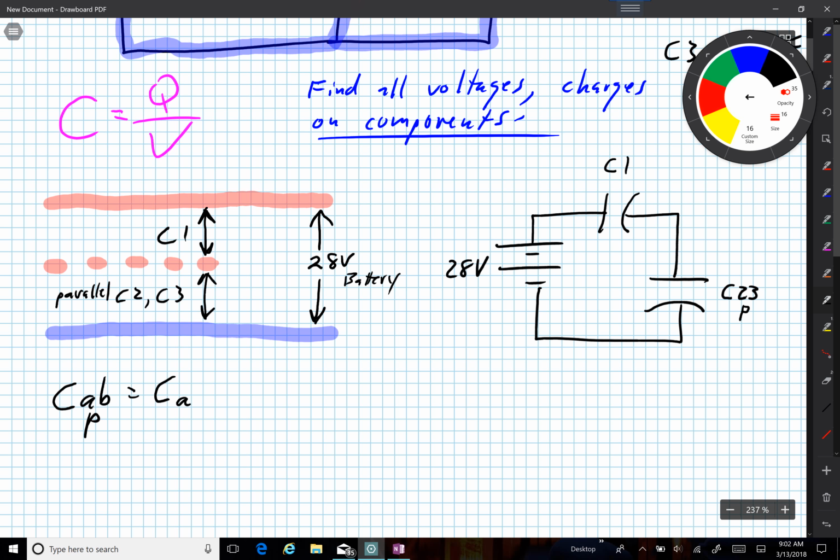They weren't in series before, but they're in series now in the equivalent diagram. C1 is not in series with anything in this original diagram. I want to make this clear. If I walk through C1, I've got a choice right here at this junction. I could go down to C2, or if I wanted to, I could also walk through C1, and at this junction, I could choose to keep going and end up going down to C3.